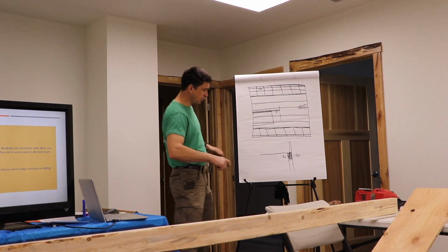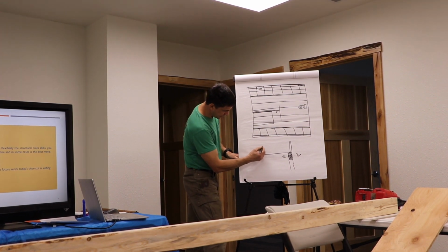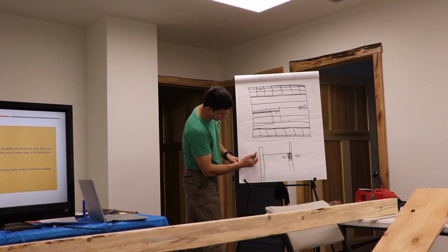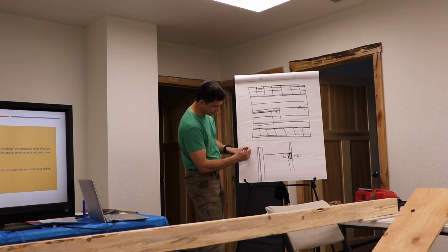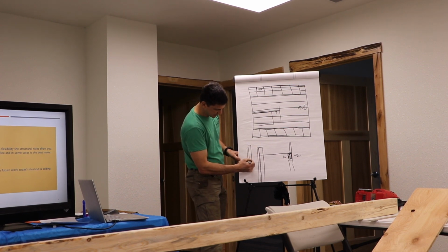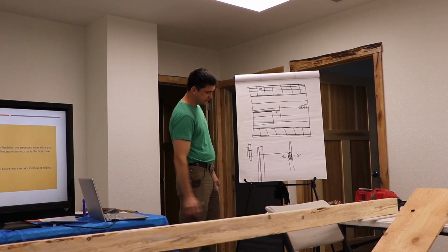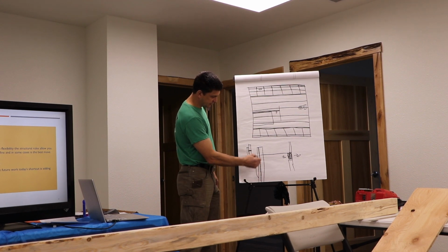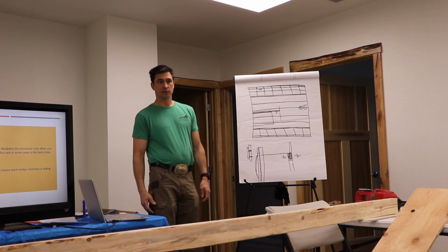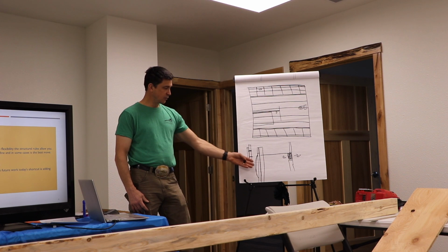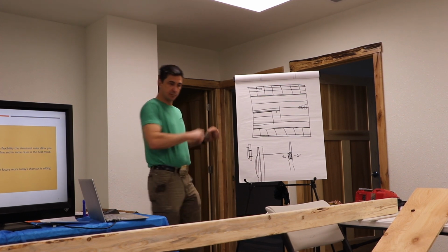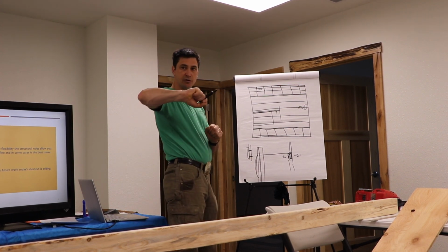So you frame a wall, here's our one wall, and then we have our other wall intersecting, and we have this 1.5-inch stud here. From the top down, you have a 2x4, and a lot of guys will then stick a 2x6 on the back of it and nail them together. But if this thing is crooked, then when I put my drywall on, I have to push that over to straighten it out.